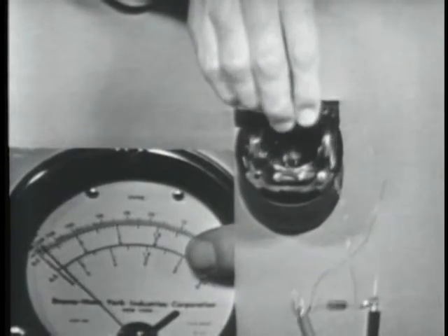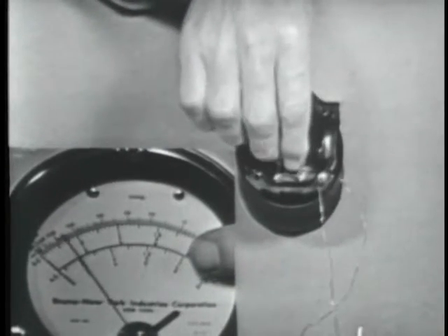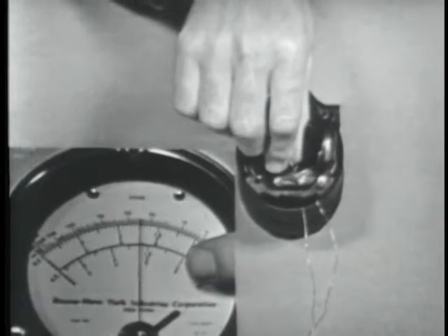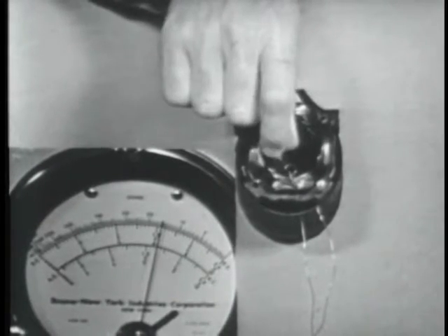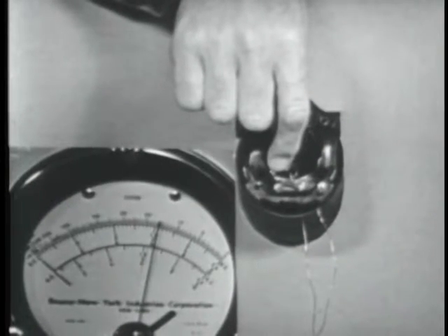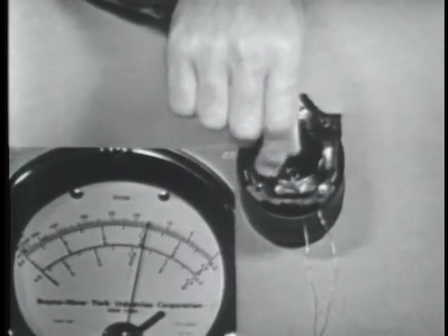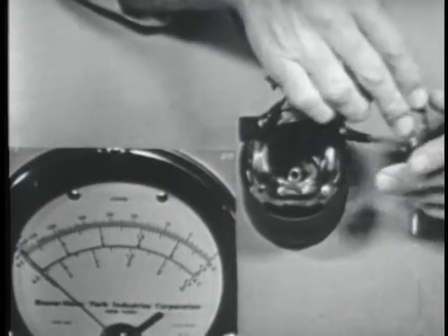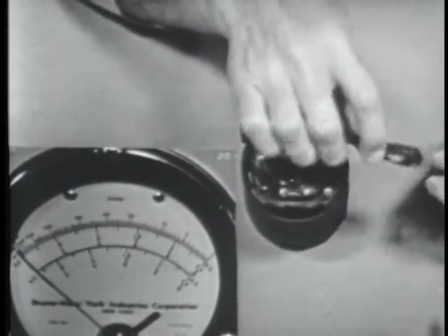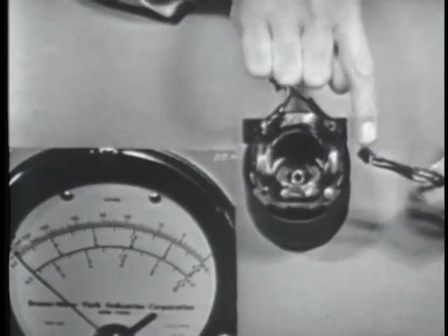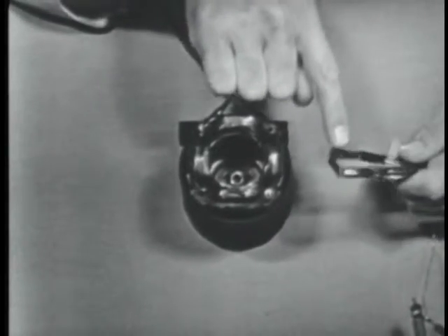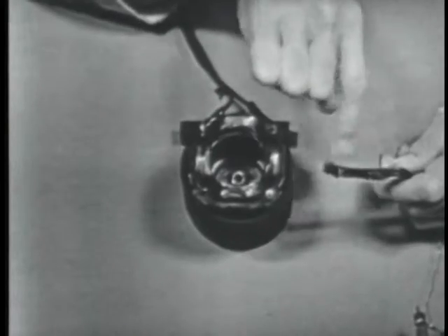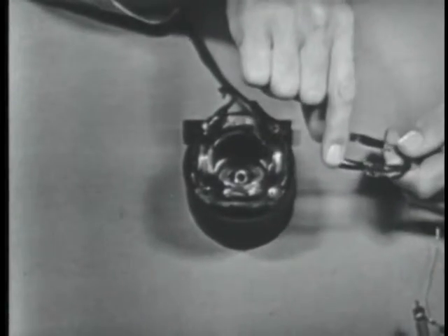And you can see that I take the loop out, it goes away, put the loop back in. I've got to get the loop all the way down in there. There you go. Now we have the rotating magnetic field inducing a voltage into the loop, which we're reading on the PSM6. Now the important thing to realize here is that once we get a current flow in this loop of wire, we have a magnetic field established about the loop.